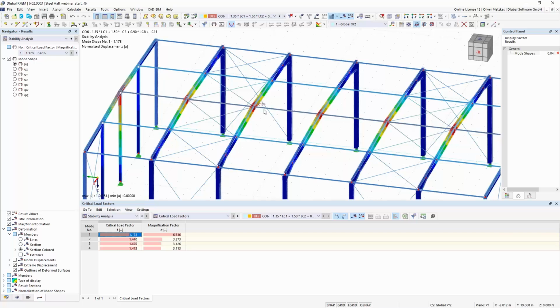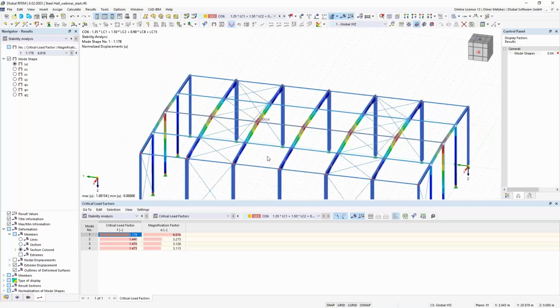So you can see that this stiffness is directly considered of all the adjoining elements, and there's no need to calculate a certain equivalent spring stiffness, for example, in this 3D analysis. So you can use this combination stability as a structural stability add-on and torsional warping add-on also to perform detailed stability analysis on 3D models with member elements. Okay, so I think that were the examples that I wanted to present you and the two add-on models. Now I can give back to Andreas.